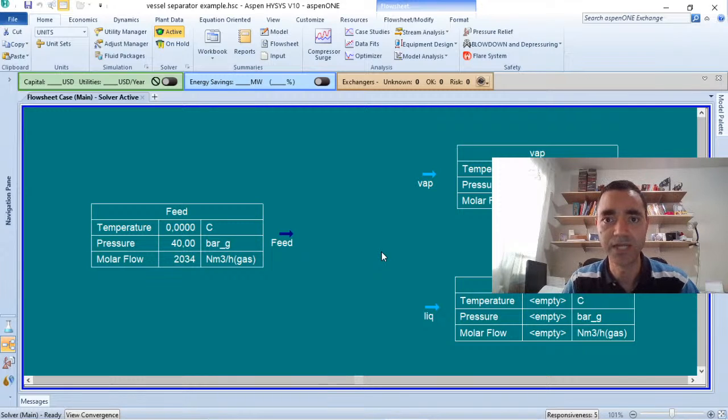But if I have some kind of failure in my heat exchanging system, I can have a temperature drop in this stream, and because of that I can have condensation forming in the line. So to prevent the condensate from reaching my customer, I need to have some kind of device to collect this condensate. So what I will show here to you is some of the considerations that we made when we were doing our plant design.